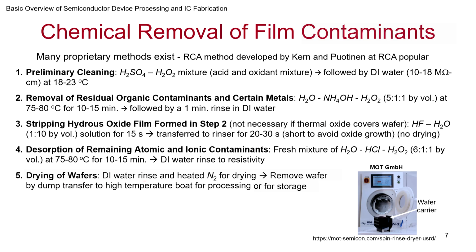In this, DI water is poured on the wafers, and very often you may have these types of dryers that are available, where first it's like a washing machine sort of thing, where you have this wafer cassette which is loaded into that, and then water can be sprayed onto it, and then it will rinse it for some time, and then it will spin it. Or you could even rinse it in a bath and then put it into this faucet dryer, depending on what setup one has.